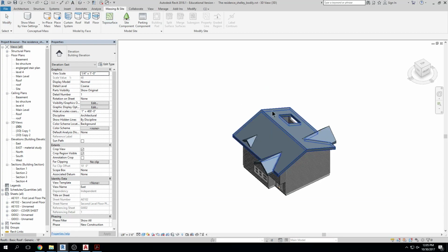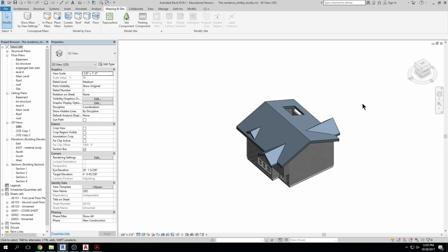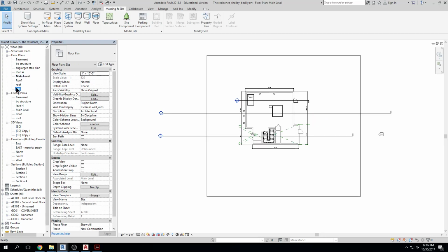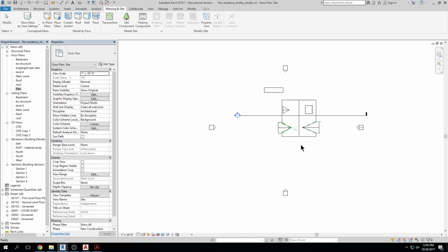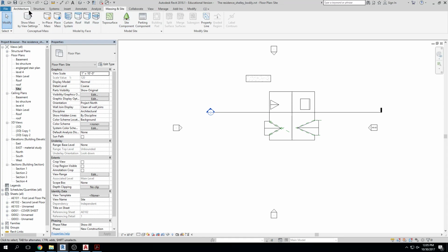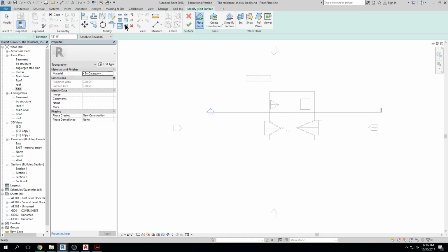All right. So we have our little house, and we know how to generate a basic topo surface. I'll do one more. How do we filter out that infill that gets in the lower level, in the basement or inside of the house? So let me create a quick one of these. Topo surface, create from points, right? We'll do 0 over here.